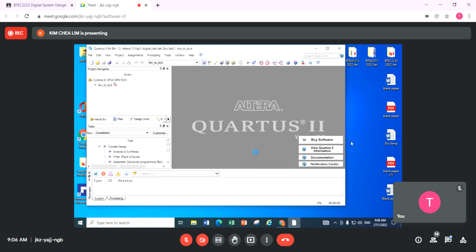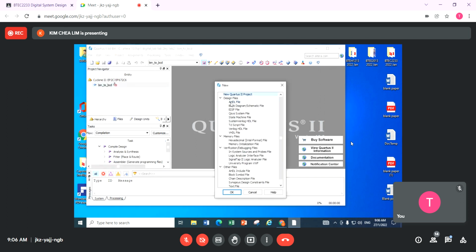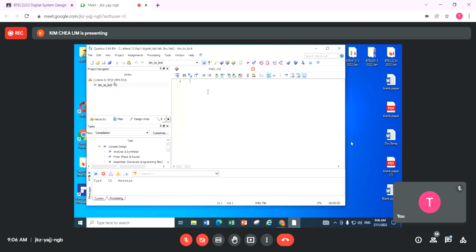I finish. And now, okay, you are going to find that when I click into this, they will still tell me that the file is not there. So I go to File, New, because I don't have this file yet. And over here, because now I'm doing VHDL, make sure you choose VHDL file. Okay, then you start to type.